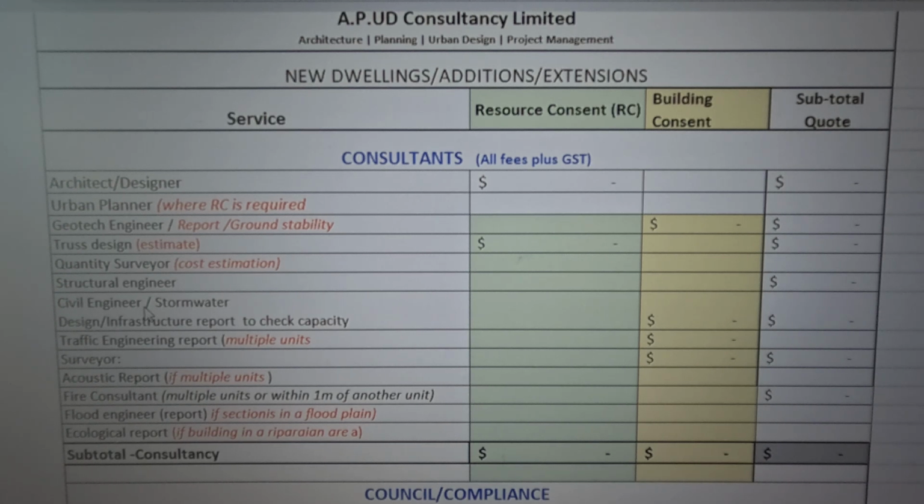to take on the extra dwellings that you're going to put in place. And then you're going to need a traffic engineering report, because you're building multi-units. You're bringing in more traffic. Remember, if the section was having 1 unit, now you're bringing in 2, 3, 4, 5 more units. You're going to need a traffic assessment done, and that is referred to as a traffic engineering report, or an engineering planning assessment or whatever.